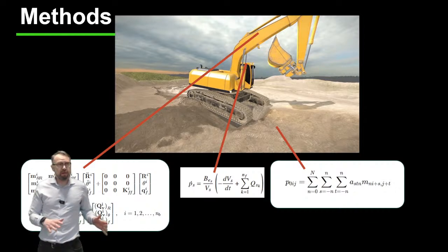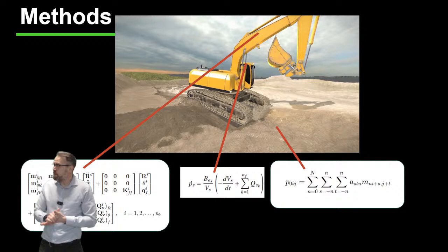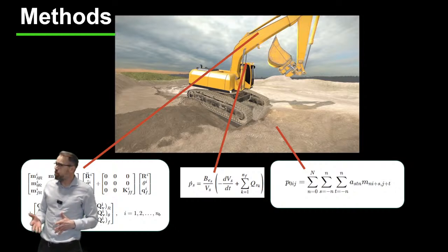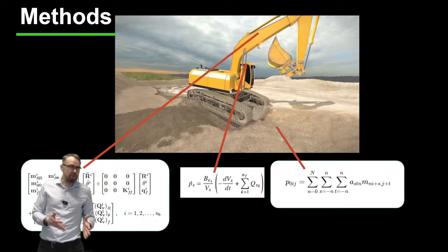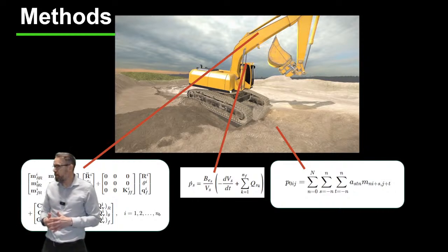So as mentioned, I've been working with multiple different formulations within multi-body system dynamics. Like shown on the left side of this slide, I've been dealing with the floating frame of reference formulation that helps to create a more accurate description of flexible bodies. This is a very critical component needed in this project too, and I need to take this floating frame of reference formulation to another level by making a more accurate description of modes that could be based on the mixed finite element method.